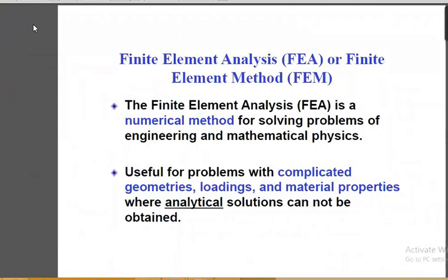So in this case, you can simply apply your basic principles to find the stresses acting on this rod due to this 100 kilonewton force. You can use the formula: stress is equal to force upon area. Force is the externally applied load of 100 kilonewton, and area is the cross sectional area, because this cross section is circular.